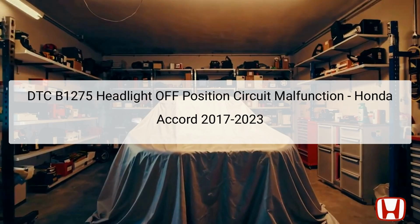Staying aware of this DTC is important for troubleshooting potential headlight issues, ensuring safety and compliance with road use regulations. Other DTCs in this context, B1276, B1277, B1278, are related to different positions of the headlight switch, which aids technicians in pinpointing the source of the lighting failures. These codes should be considered collectively when diagnosing the vehicle to rule out broader electrical problems across the headlight circuits.